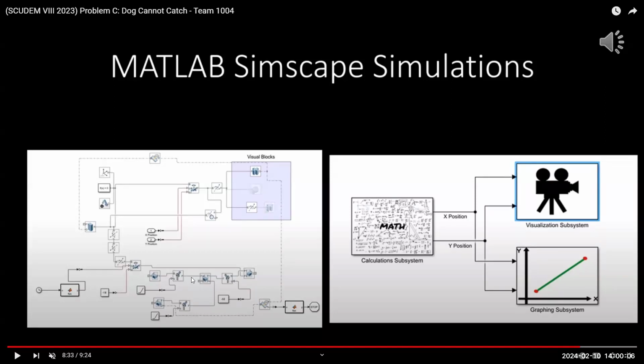For instance, if two parts are allowed to move in the X and Y plane and rotate in the Z direction, it'll put that exact joint in your Simscape model. And that can create confusion when I'm going through the model and trying to perfect it and make it move properly. So usually I just start off with a rigid SolidWorks assembly model, and then I put the motion in Simscape. But I know I've had problems in the past where the way things are constrained in SolidWorks makes it a lot longer for me to actually make the Simscape model.